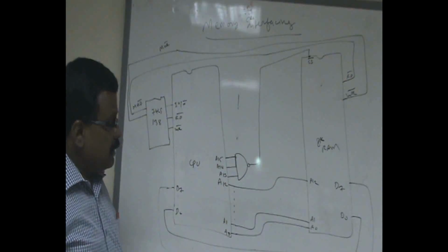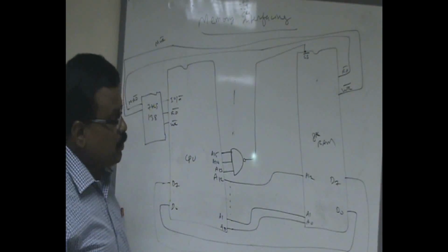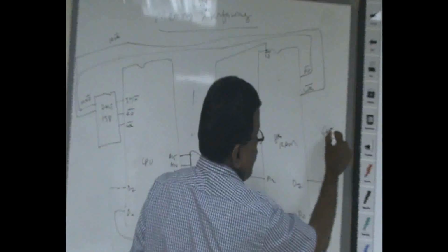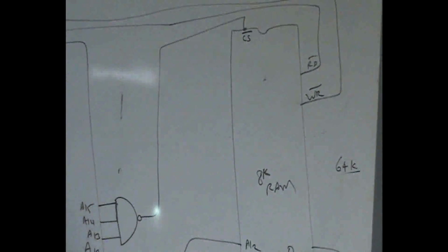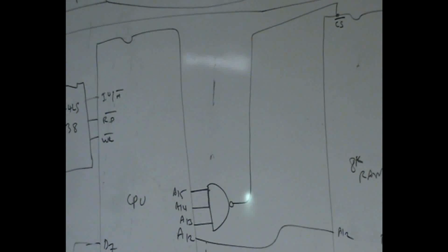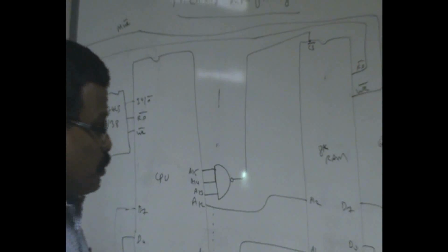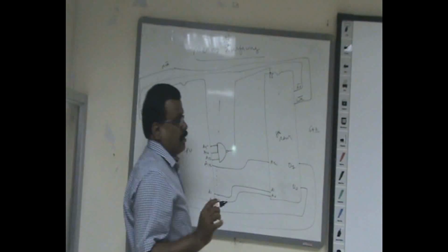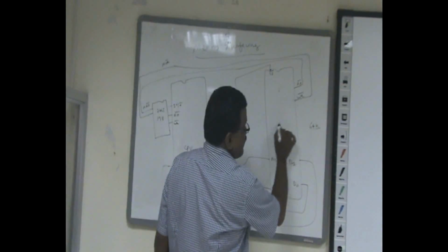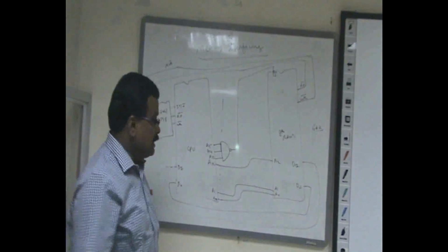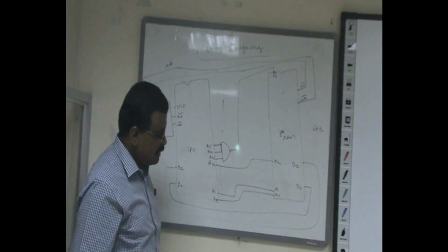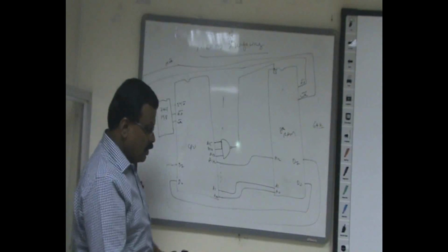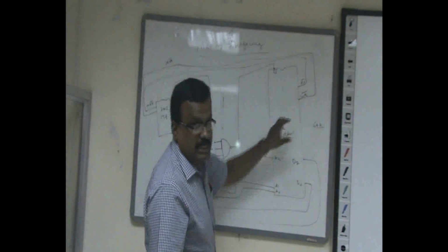Now the next step is, you have to find the address space. Suppose the total number of memory locations available as far as 8085 is concerned is 64K. In the case of 8086, it is 1 MB, where there are 20 address lines. Now you should go for another thing which is called address mapping, because within this 64K, this 8K RAM can be mapped anywhere. That is based on this decoding logic. Suppose the decoding logic is like this, let us see what is the address map of this memory.